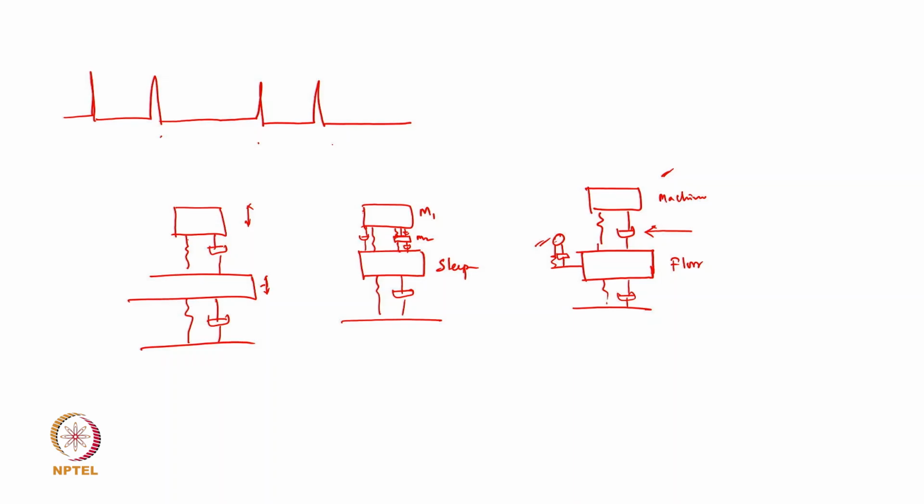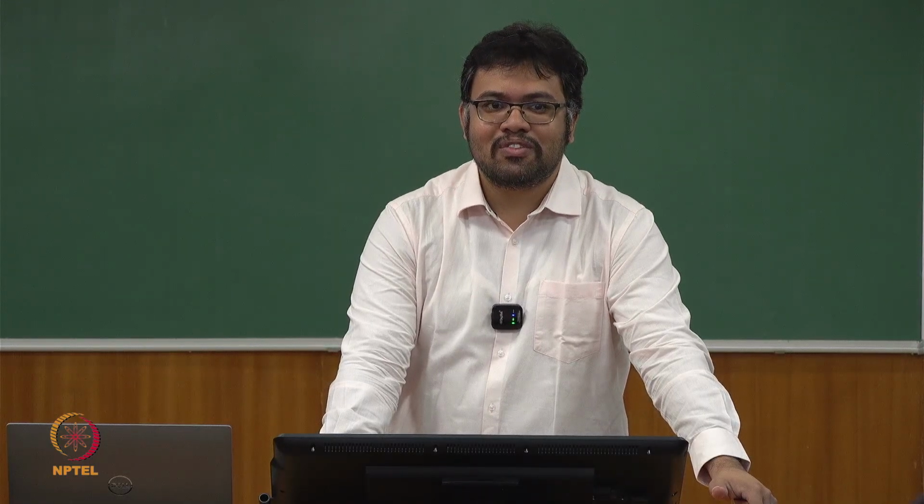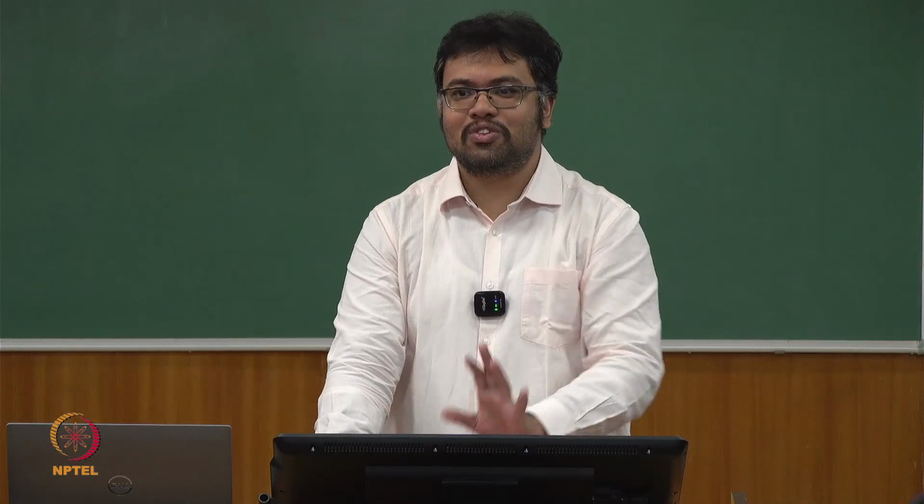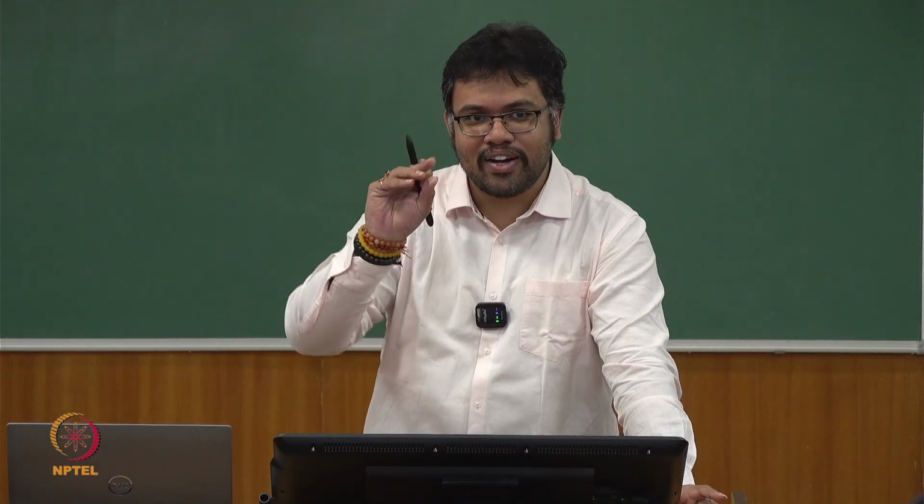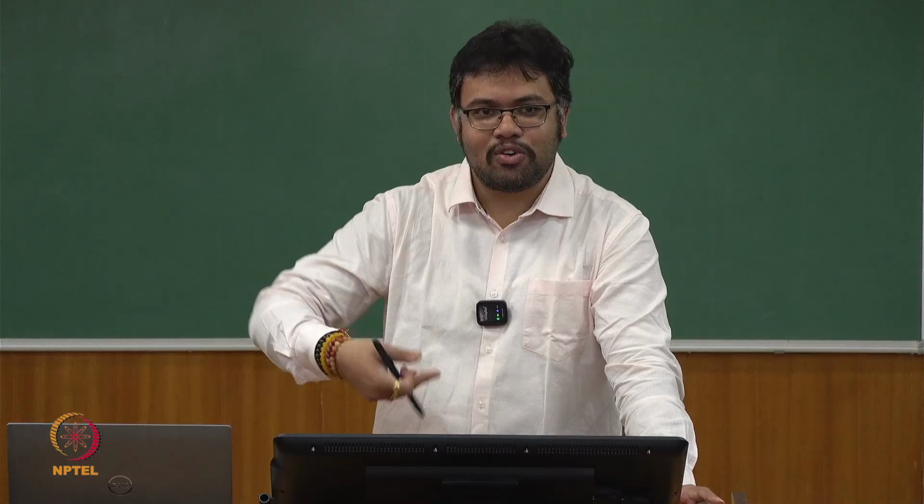Okay. And also, I would like to say that my full PhD research, and people who know me a little bit know this, is the metamaterial topic. The fundamental key aspect of the metamaterial comes from the tuned mass damper. We try to design this type of tuned mass damper inside the material system, so that the material system itself can do the vibration control instead of going for any other special layer, like the pads and all those things we are designing. They all have that impregnated resonator, so they can oscillate and insulate the vibration by themselves without going to some other places.